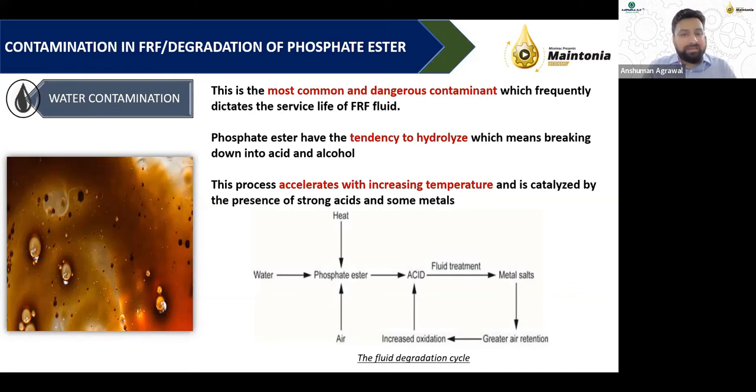and the team who needs to take care of it certainly needs to take a step forward, start analyzing what went wrong, why the valve has failed, why the system has not performed, and what the traceable linkage is between the phosphate ester fluid contamination and the failure at your place. There might be situations where you just want to hide the reason under the blanket, but trust me, this reason would come again and again in front of you. You can never get off it, because once your fluid has degraded, there is no alternative but to bring it back to its original shape.